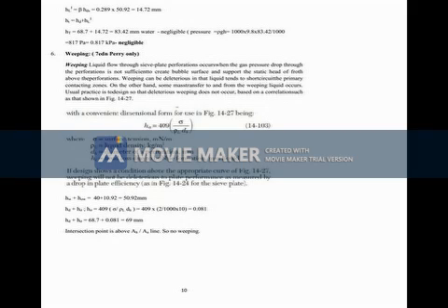Now, next we have to check for the design adequacy. Next you have to find out the pressure drop. Total pressure drop HT is equal to HD plus HL dash. HD is the pressure drop across the dispersion unit, and there is a formula to find out HD: K1 plus K2 into (rho G by rho L) UH squared.